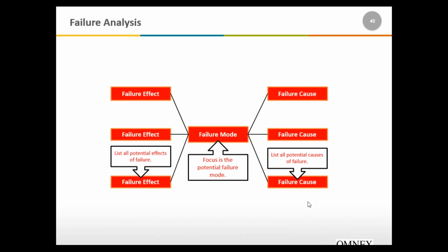So this is graphically what you would be doing on the form, or what you're even doing in the current approach. You have the failure mode, and then you ask the effect, where in the current way we would be brainstorming. Under the new FMEA, because we have built the information about our higher level, we can just associate the higher level failure modes as effects to the focus failure modes.